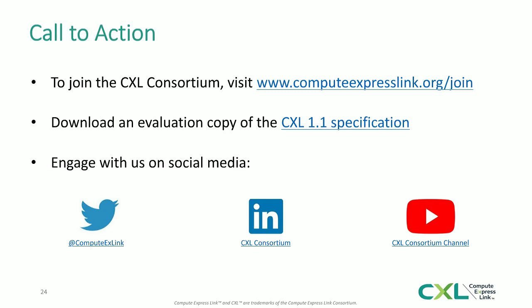As I alluded to earlier, there is going to be some amount of added latency here. You are moving from a CXL interface and having to translate that to some other media-specific interface. So there will be some amount of added latency. Having said that, CXL was designed from the ground up to focus on minimizing that latency as much as possible. So all of the layers in the CXL stack were designed for low latency.